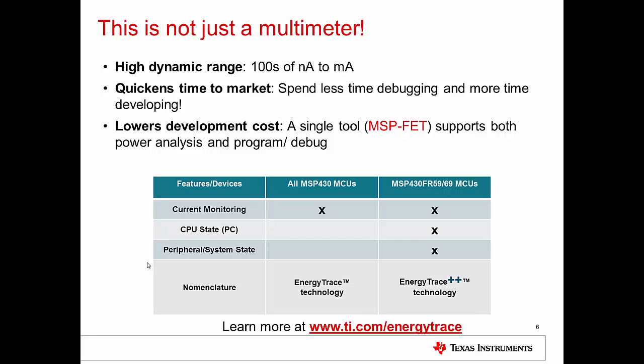There are two terminologies here that I really want everyone to be aware of. The first one is the EnergyTrace technology. The next item is the EnergyTrace+ technology here. The EnergyTrace portion of the EnergyTrace technology allows you to measure or monitor the current, and it is supported by all MSP430s.